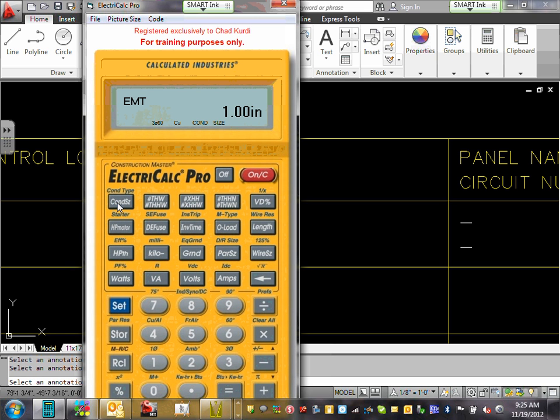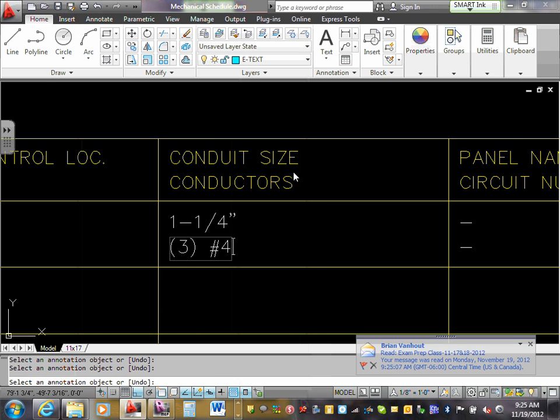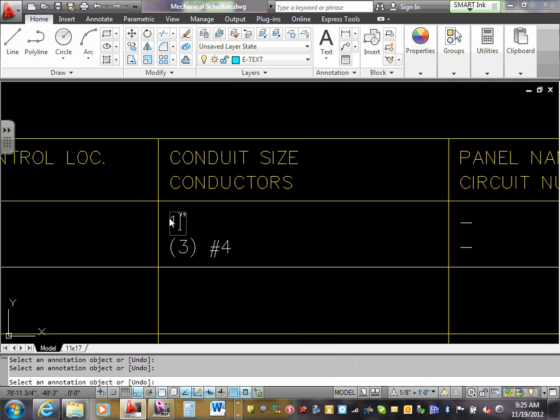If I'm inside the building, don't you think EMT is your conduit of choice? The only time you don't use EMT is if you're outside the building or underground. Okay, so that's an answer. Do you guys have any problem with that? If you have any problem, wait for me at the end of the parking lot. We're going to use the shell as your grounding. When you reach the unit, obviously you have to flex it and tie it, but okay.